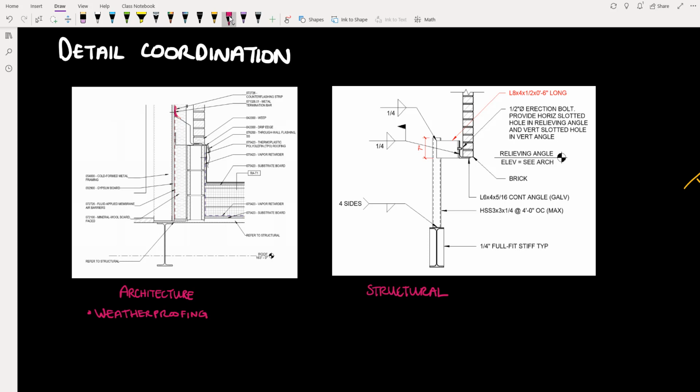And so they designed flashing for water that gets inside the cavity here to be able to have a path back out. And that flashing needed to occur above the insulation. So you can imagine if they tried to flash down below here, it would not work because the water would run into the insulation, and we don't want water inside our insulation. So that flashing had to be kept high.